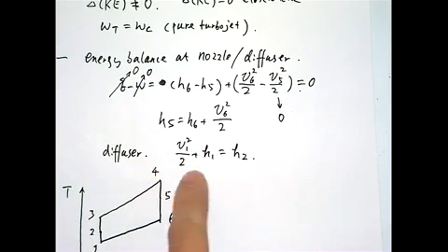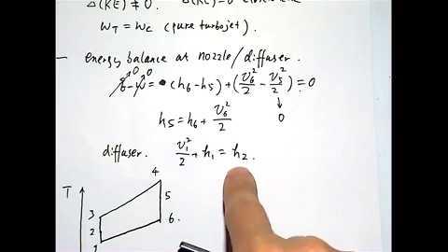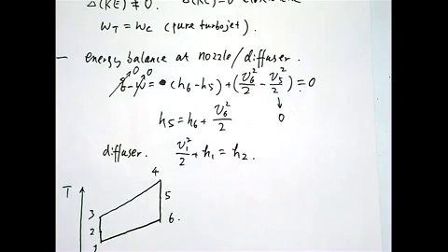Sorry. The diffuser is a process that converts kinetic energy to enthalpy, which we do here. So going from 1 to 2 is a diffuser, right? You have the kinetic energy coming in. You consider that the aircraft is flying at a pretty high speed, and the air is coming in at a certain velocity, and that velocity, when going through the diffuser, is used to raise the enthalpy of the gas. High enthalpy means high temperature. So that's why it's going up here. But point two is at the beginning of